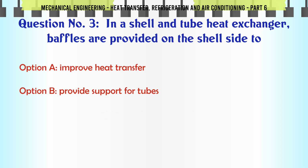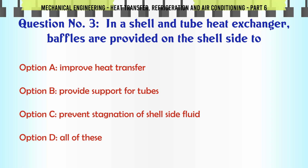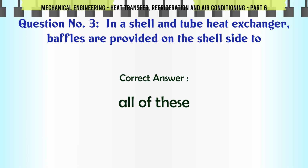In a shell and tube heat exchanger, baffles are provided on the shell side to A. Improve heat transfer, B. Provide support for tubes, C. Prevent stagnation of shell side fluid, D. All of these. The correct answer is all of these.